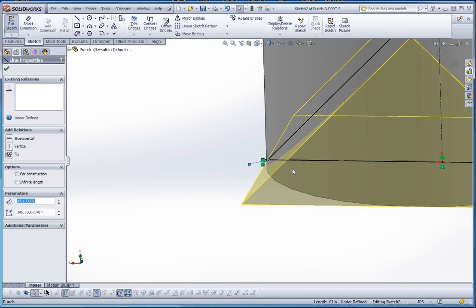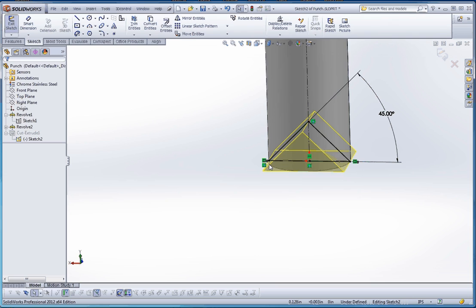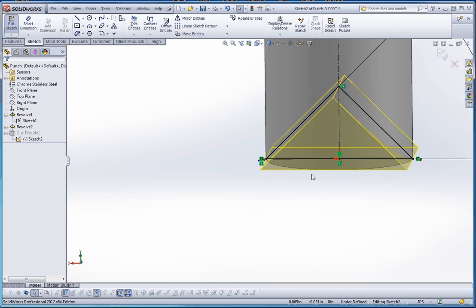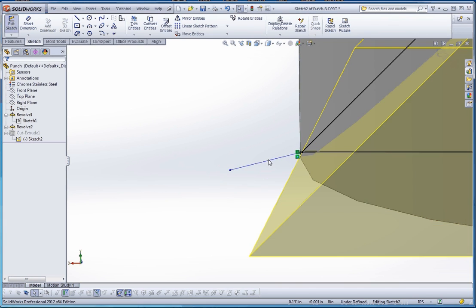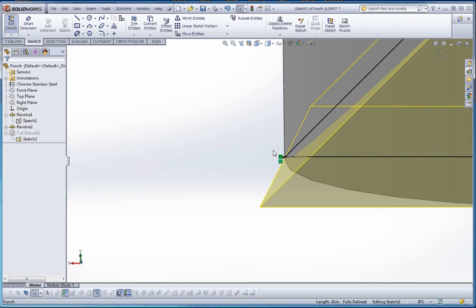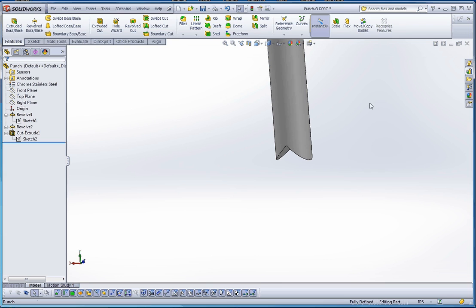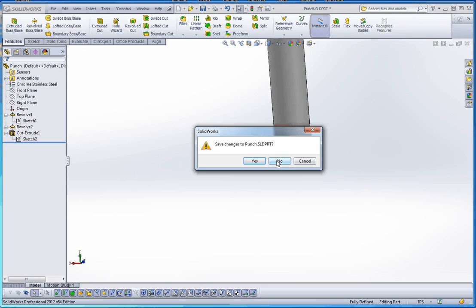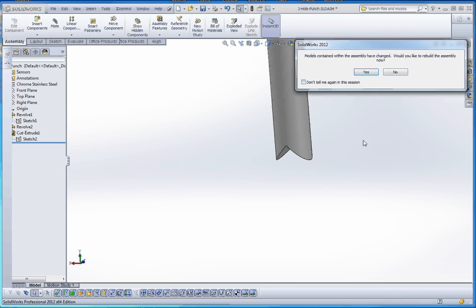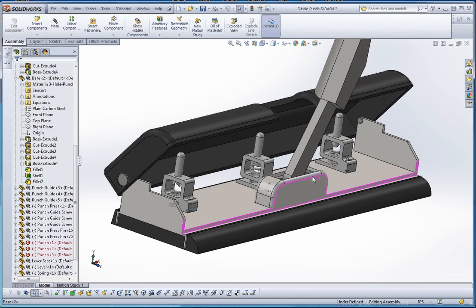But if you look towards the corners down here, you can see extra stuff down there. And that's kind of an indication that you have that. And sometimes it comes out as blue. So let's go ahead and delete that because we don't need that. If you go to rebuild, now we're in pretty good shape. So let's go ahead and close out. We don't want to save that, but yes, we want to keep the model geometry in there, in memory.